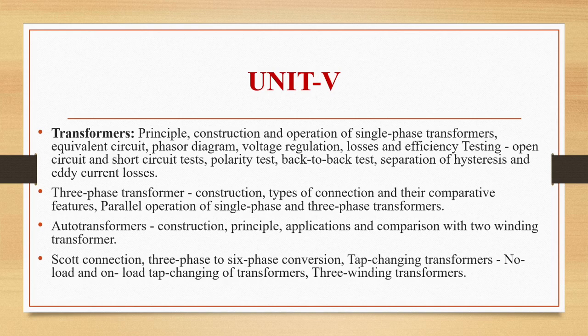Okay. So why are we giving AC only to a transformer? Does a transformer work on DC? No, a transformer does not work on DC because, if a DC voltage is applied, current or voltage will not change with respect to time, and EMF will not be induced, because there should be a change in flux linking with the coil for the EMF to be induced. But if there is no change in flux, no EMF is induced. So that is why a transformer will not work on DC. It will work only on AC.